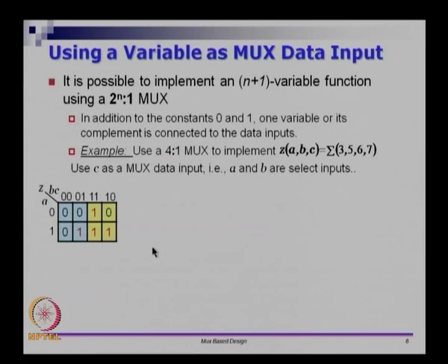We have that, and once we have this, let us see how to get C out of this. So you go and look at combinations a pair at a time. You look at these two cells here. In this case C is changing from 0 to 1, but the output is not changing, the output is remaining at 0. Even when C changes from 0 to 1, the output is 0, so you put a 0 there directly. Here, if C changes from 1 to 0, F changes from 1 to 0, which means F is changing as C is changing, so you put a C there also.